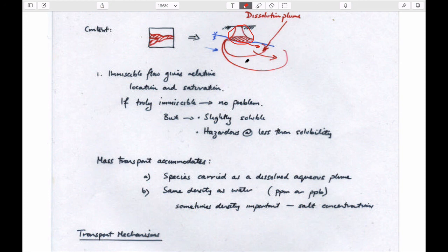And the things that we'd like to know are, what are the concentrations at all of the locations within this plume that develops as a function of time, presumably it'll get larger with time. And also, if you have a compliance location where you're taking water out from downstream, when does stuff arrive? So if this is time, when is it that it arrives and we have to worry about it? And so that's the deal.